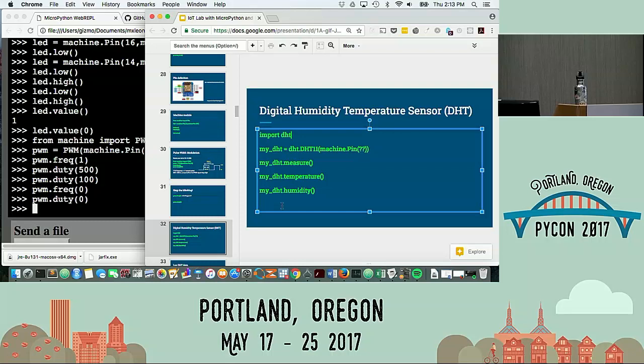The numbers are not matching here. The numbers on the D0 are not matching these ones. So that one's going into D0 here, and you wanted to set it up for PWM? Right, so what you can do is move it up one. Do you see that's D5 there? If you move this connection here, and then look at the pinout sheet, do you have it? Yeah, here. Okay.